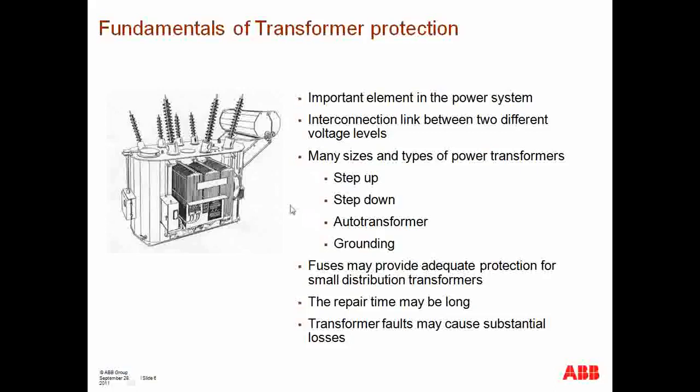The third type that's also commonly found would be an autotransformer, which, from a transmission network perspective, is a device usually utilized to interconnect two transmission networks that are operated at two different voltage levels. So, for example, if a utility operates a 400 kV loop and they also operate a 230 kV loop, and you wish to connect those two networks, typically you would utilize an autotransformer, or perhaps a Y-to-Y transformer, which will allow you to connect those two voltage levels.